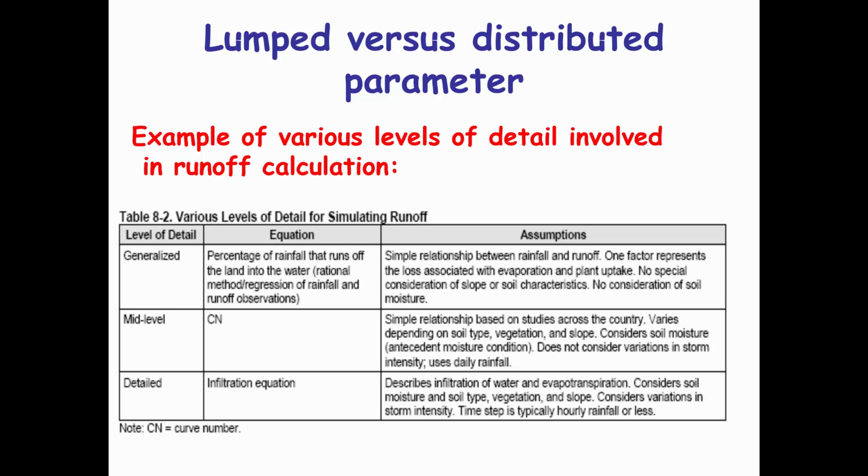With this, you're able to calculate how much runoff would be generated from a given rainfall and a particular storm event. Again, this method does not show how the runoff is distributed during the rainstorm event. It only calculates how much runoff is generated from the amount of rain that falls within a particular rainstorm.